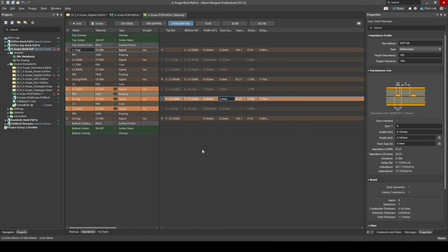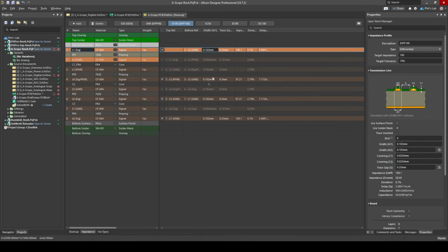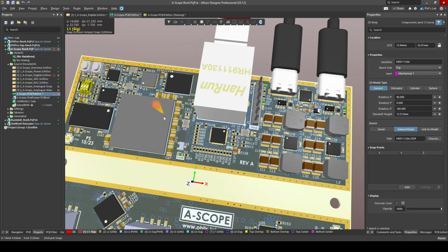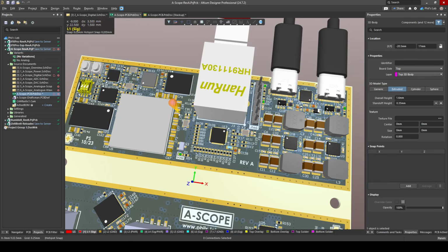And the reason these trace widths are so narrow is because the dielectrics are thin and I need 50 ohms and 100 ohms differential, which drive down these trace widths, because I'm also fanning out a BGA package and I do need very narrow trace widths to get past the via grid and the ball pad grids as well. So that's why these trace widths are rather narrow to hit these impedance specifications.